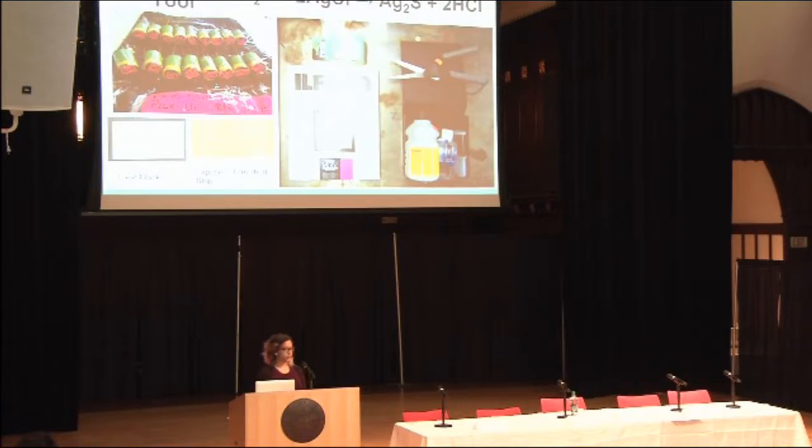So we developed this tool based on the fact that it's a corrosive gas. Hydrogen sulfide reacts with silver embedded in the layer of gelatin on photographic paper, and then it tarnishes it. So we can look at the level of tarnishing on the photo paper to see if an amount of hydrogen sulfide is present. This field on the left side, you see it's mostly white.